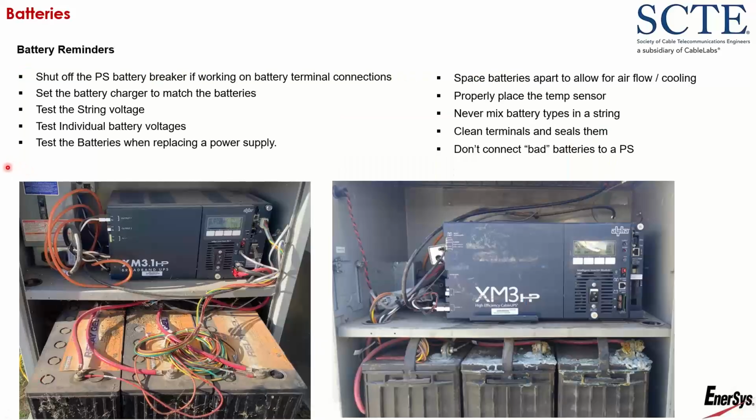Some battery reminders. Shut off the power supply breaker if working on the battery terminal connections. Set the battery charger to match the batteries. So you really want to match your charger to the battery type you're using. That will optimize the charger for those batteries, extending the life of the batteries.